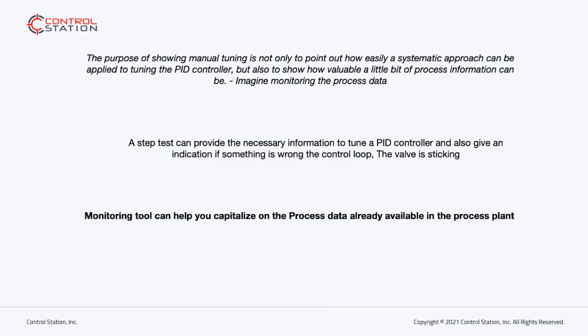You can pick up tuning issues, as I mentioned with the example from my professor, where a poorly tuned controller can have a profound effect on the plant-wide performance. And identifying these tuning issues can be challenging. Monitoring the loops makes it easy to assess the effectiveness of each PID controller and the tuning relative to the associated process performance.